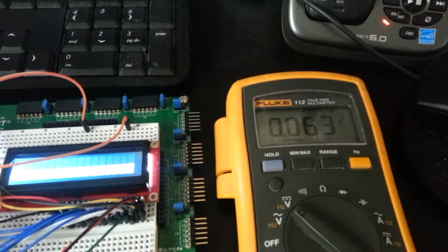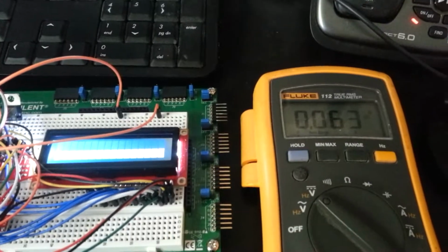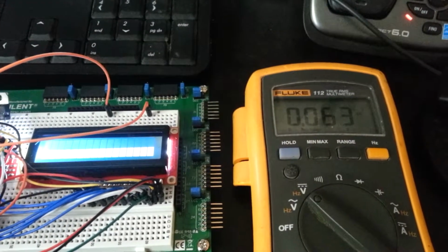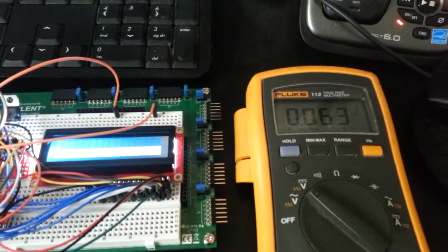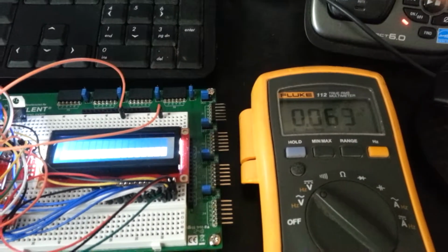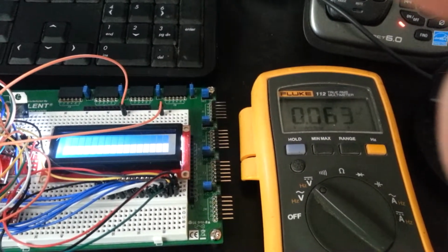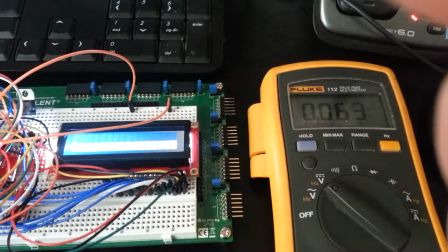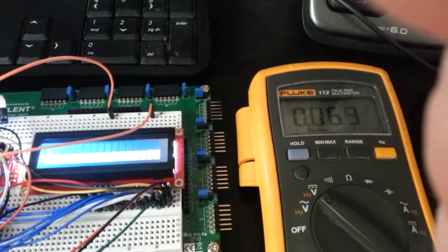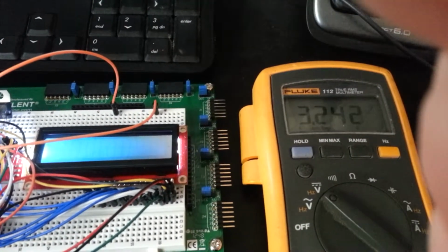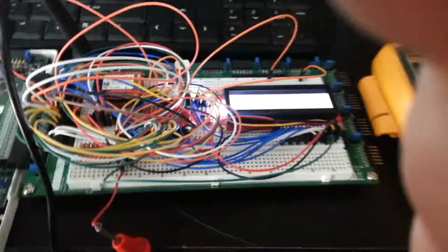So basically what this digital potentiometer is doing is, as I'm sending codes through the enhanced SPI interface, it's decoding these 8 bits that I'm sending, and it's adjusting where the wiper location is on the internal potentiometer. So let's go ahead and begin again, and we'll see it go to nothing on the display, and that brought the voltage all the way up to 3.3.